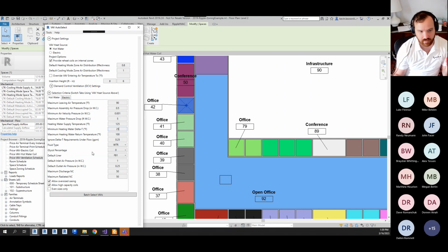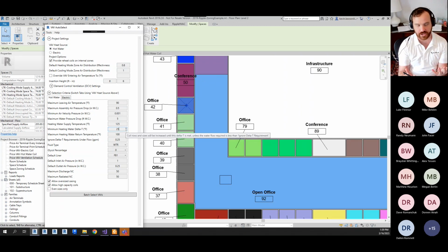So you can't make the air side BTUs equal the heating side BTUs exactly because you only have 6 options. Now, you can do that on an air handler coil because Trane or whoever will custom build you a coil to match your performance exactly. That makes sense to do on a $200,000 air handling unit. It doesn't make sense to do on a $1,000 VAV.